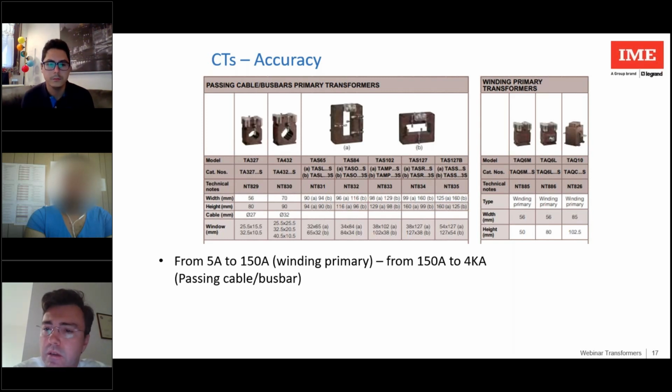So it depends not on the current transformer, but on the measurement instrument, the wiring diagram of the measurement instrument. Dina, does a fluctuating power factor, for example 0.75, have much effect on the accuracy of the CT? No. As I say, the current transformer takes the vector current from the primary and reports it to the secondary as it is.